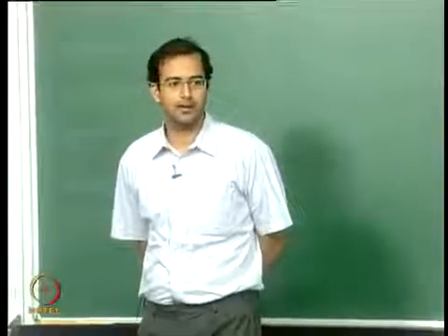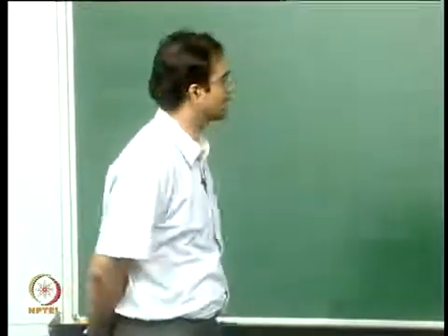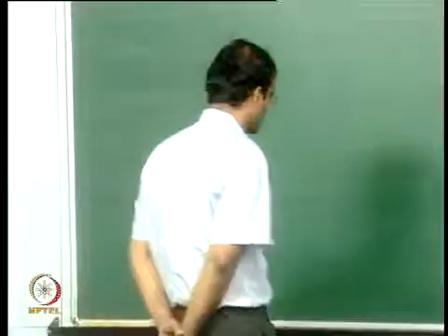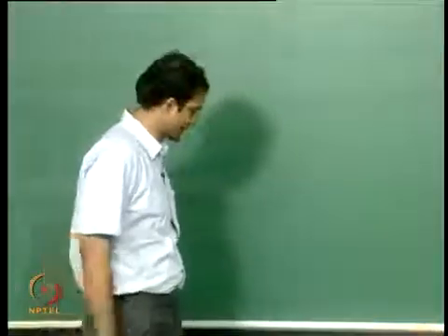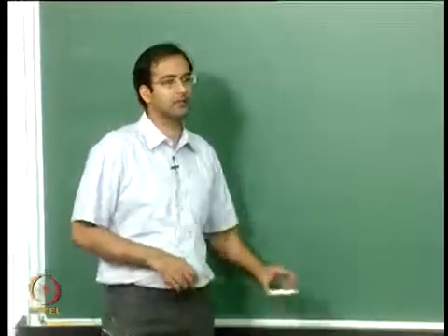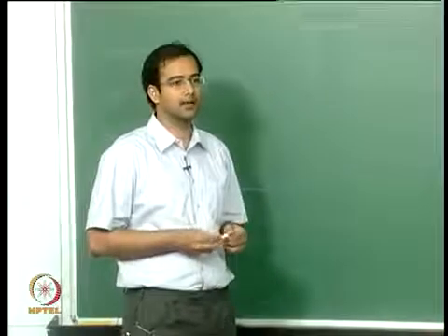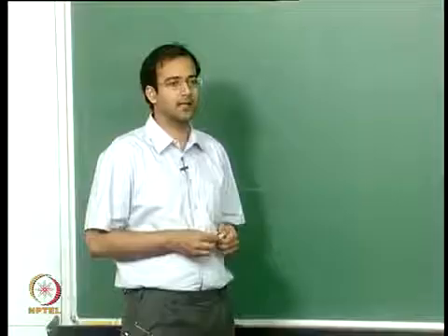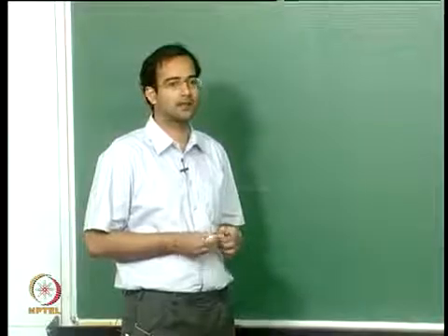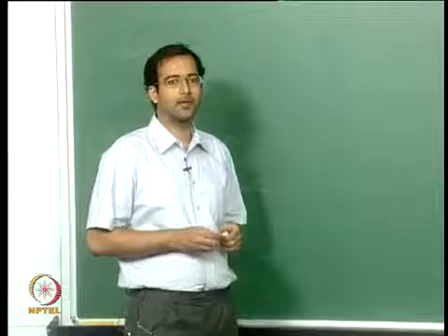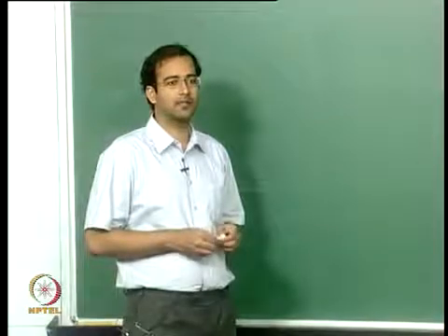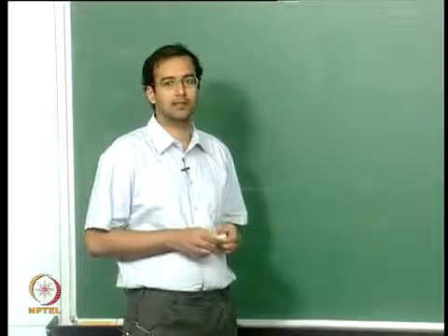So today we will look at a different kind of solution to the extended Graetz problem. The original Graetz problem was done, as I said, for the case of a plug flow with a constant wall temperature, and that was extended later by Sellars to a parabolic velocity profile, and we also saw the solution to that. So now we will quickly visit the last of the extensions, that is with a constant wall flux boundary